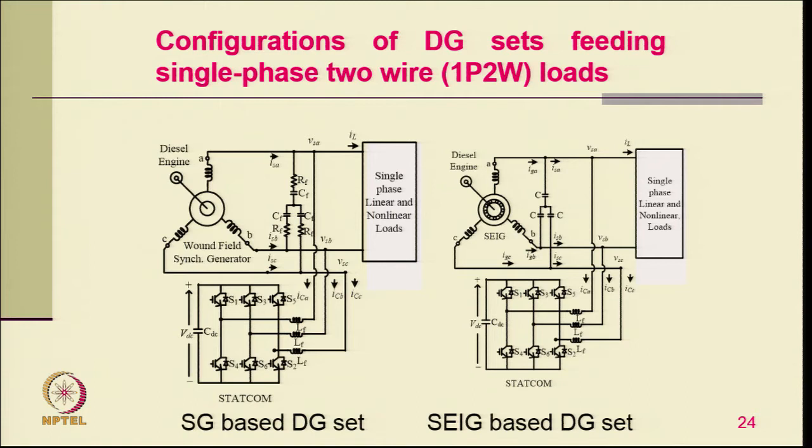I can tell you a very interesting major problem. Sometimes these DG sets have to be derated if they are used for feeding a non-linear load or a single phase load, like a telecommunication network. Those DG sets were derated; typically even a 25 kVA DG set was used for only a 10 kVA load, because it was a non-linear load, and when you have a non-linear load, certainly you have to derate.